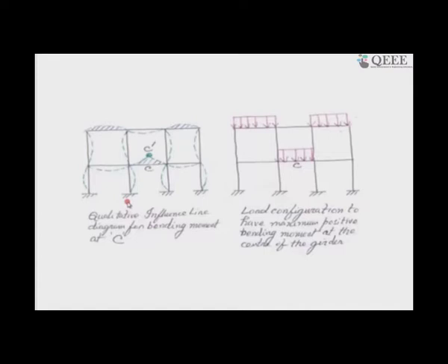We are interested in where that C is written, the bending moment at the middle of this beam, the influence line diagram for bending moment at the midsection. Obviously, the midsection of a beam might be subjected to the highest sagging positive bending moment. That is why we are suspecting that it should be examined. Yes, and now we are examining it with the Muller-Breslau principle.